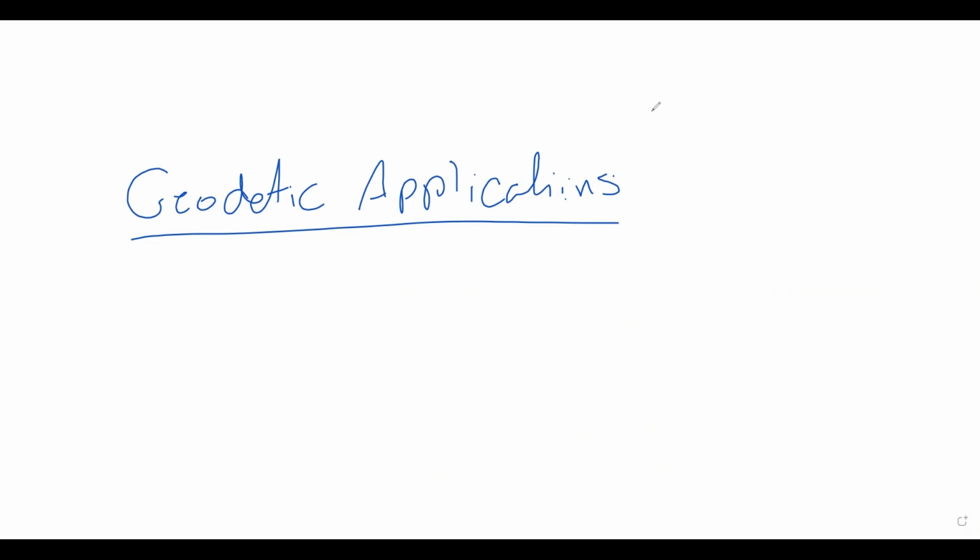First goal of geodesy is to determine the shape and size of the Earth, and the physical shape of the Earth. With the approximation of 72%, about 70% is sea level, because 72% of the Earth is covered by water. So the main goal, the first goal of this, is to determine the geoid surface for the Earth, over the oceanic area. So I wrote the equation that geoid will be sea surface height minus sea surface topography, or the dynamic topography.